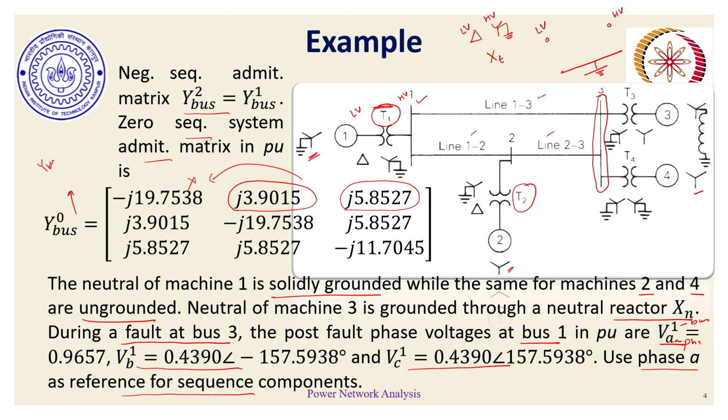So coming back to the zero sequence representation of this transformer with HV side being star grounded and LV side being delta connected, if you revisit our discussion where we have this JXT representing the zero sequence leakage reactance of the transformer, how should this connection look like? Remember, in delta connection, the zero sequence current can never escape out of the terminals.